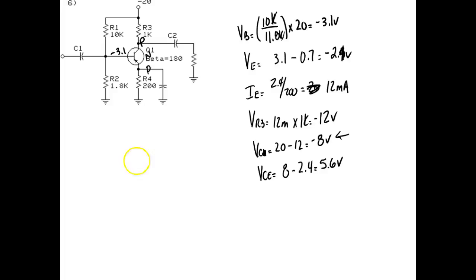Okay, so what happens is, let's pretend this is an NPN. So this is the voltage I have to work with. I have 20 volts, and then I have 0 volts. Y'all understand that? And what I'm trying to do is amplify something. If I bias it up into here, and my output starts going positive, it's going to clip it.